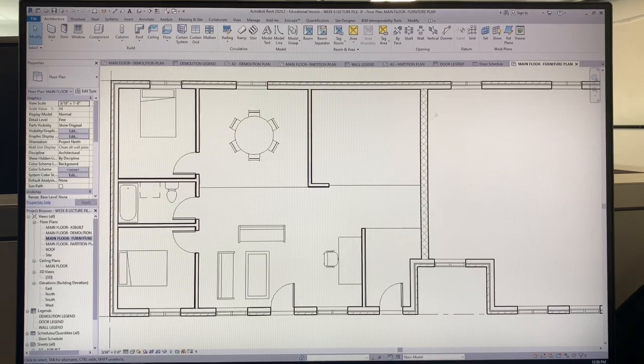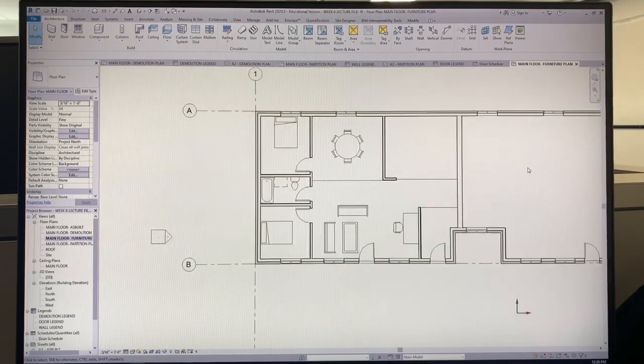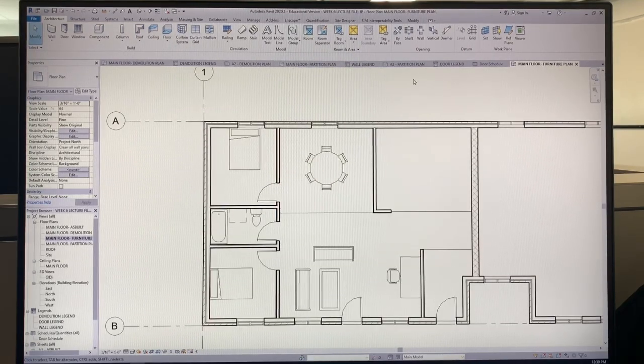And then in the kitchen, I'd have to put in the stove, the fridge, and so on in there as well. But you get the gist of it. So again, furniture, fixtures, and equipment should be placed into this drawer. Alright, next. Let's tag them, and then let's create a schedule of them. So we're going to do a tag all in this situation.